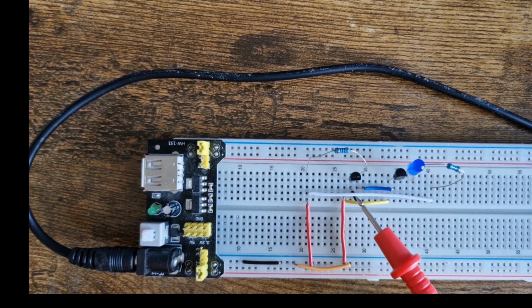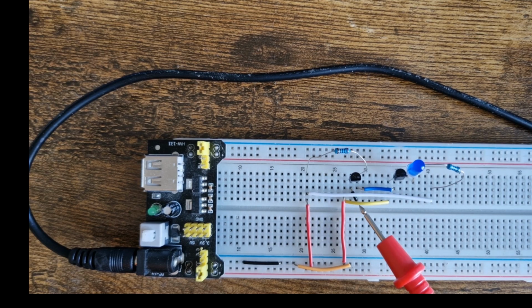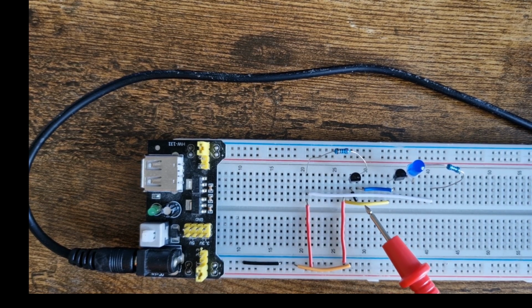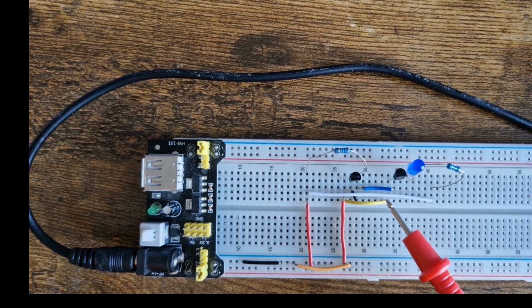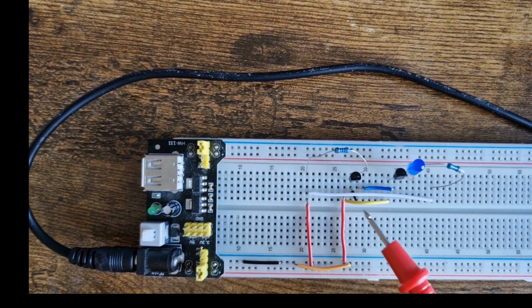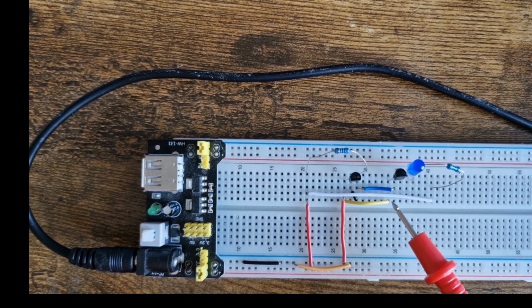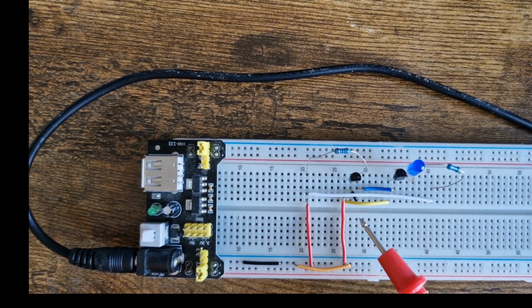For example, their collector currents are same, their DC gain factor or beta are same, their VCEO, that's the voltage between collector and emitter with base open, they are also equal. That is what all these parameters we can verify or see from the data sheet.